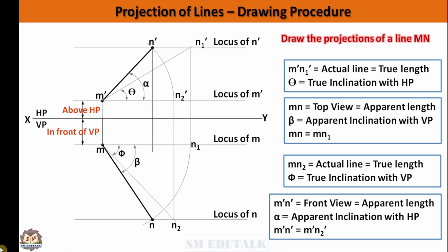It will be helpful when solving the problems. Connect the points N dash and N by a projector. Dimension the given data on the drawing like true length, inclinations, etc. Don't worry if you're not able to understand. I'll explain with a real problem.